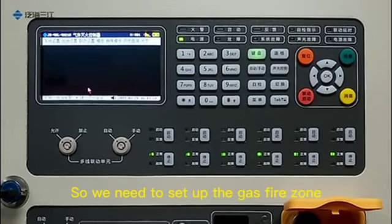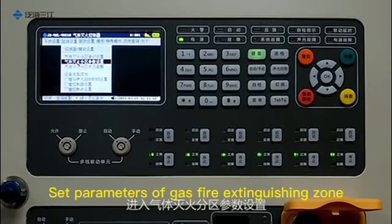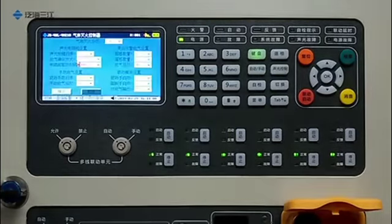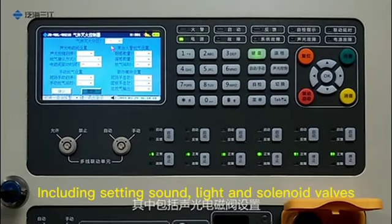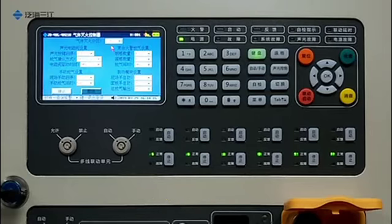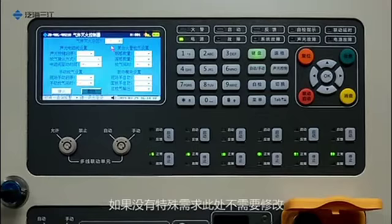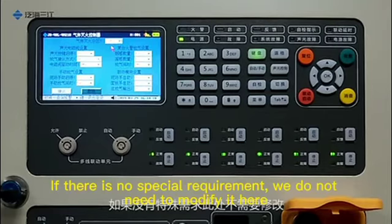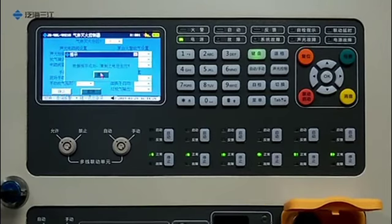Because this alarm host is mainly used in the gas fire extinguishing system, we need to set up the gas fire zone. Click on Bus Settings. Set parameters of gas fire extinguishing zone. Select E-partition. Set parameters for partition E, including setting sound, light and solenoid valves, manual gas release setting, compound fire alarm and gas release setting and linkage module setting. If there is no special requirement, we do not need to modify it here.